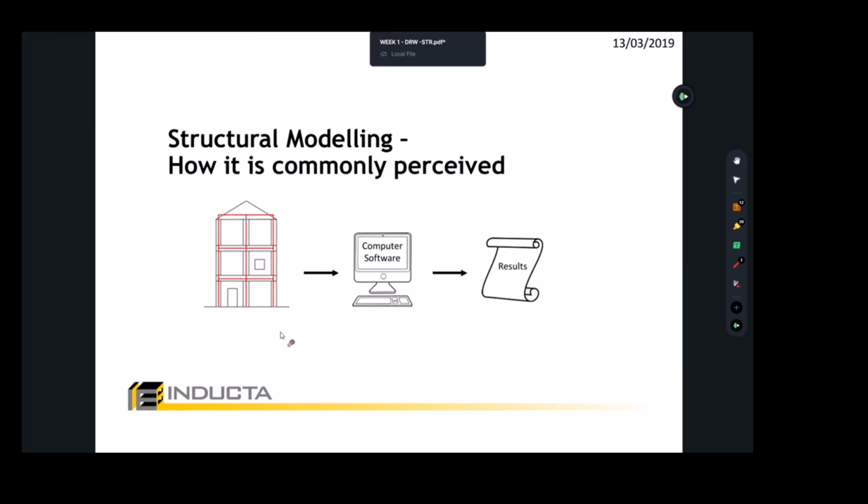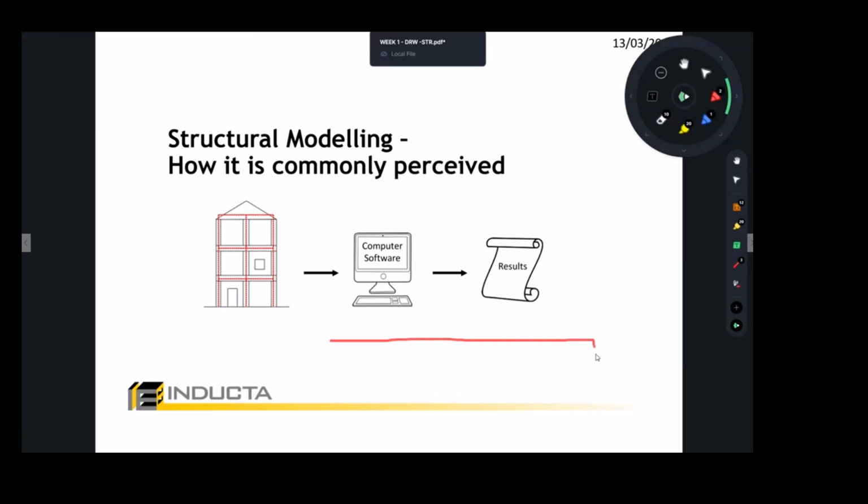That's where the structural core is located. So your thinking should be something like what the red lines are showing. Sometimes in buildings, if they are really large in terms of a plan, a footprint, then the cores cannot do the job. If you got a 30 meter long building, you would need three cores maybe, one located here, another one there, and maybe another one there. Sometimes you'll find it's really not adequate.